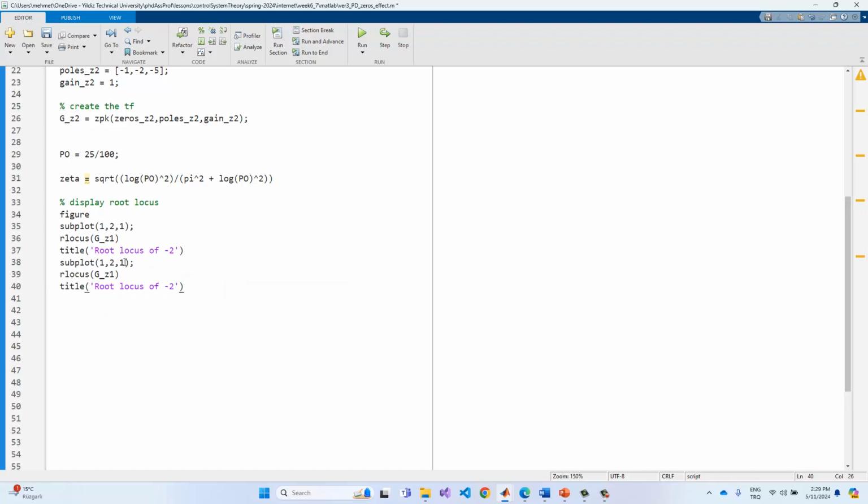And also we need to copy all of these things in here, z2 and -4. Okay, these are the basic criteria for this case. Okay, and also we need to give the grid in here to draw the line of the zeta. Okay, zeta, and also we need to give the y limit value of -20 up to 280. Okay, because the imaginary axis can be seen by this range of values. Okay, and so if I run this code, and then we will have the